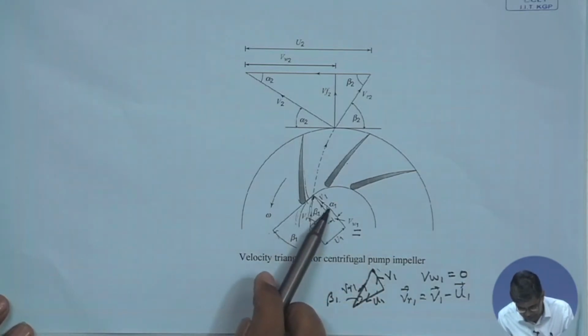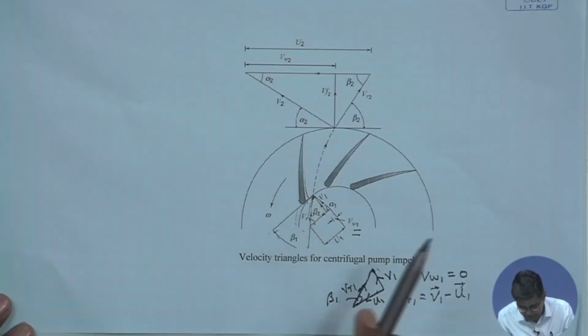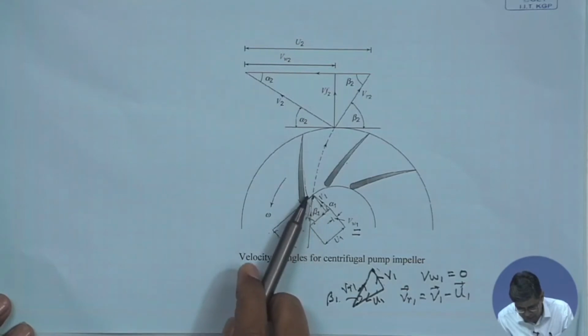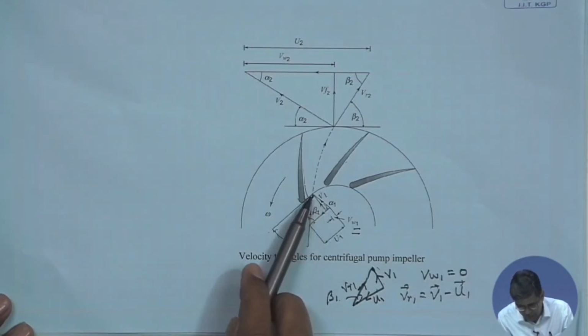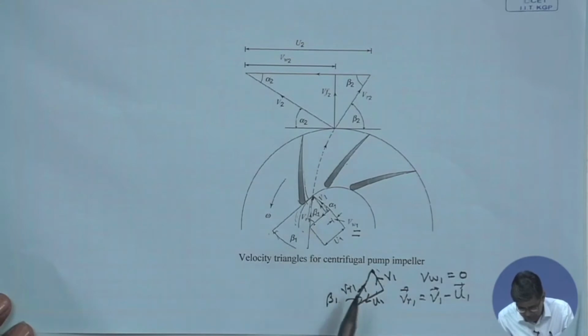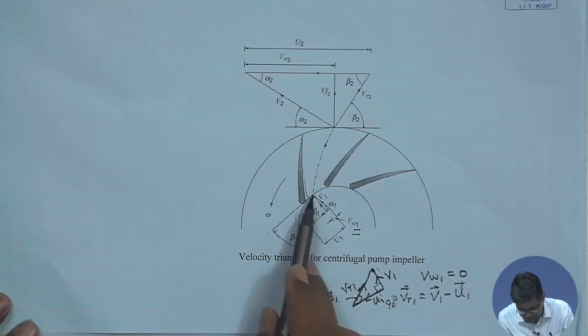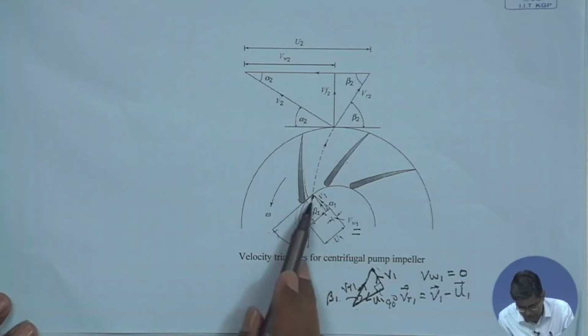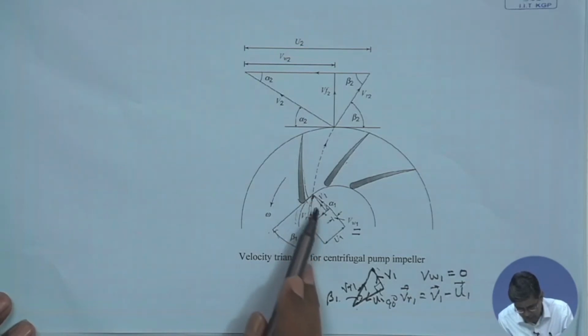So, that is why this line is given. In practice the velocity angle is like that. Nevertheless, it should be designed in such a way that even if this V1 is not perpendicular, the direction of fluid velocity is not perpendicular to the rotor velocity U, the ideal case is 90 degrees. Here also, in the ideal case, it is given by this line, but it has a very small component in the tangential direction. It has an appreciable component in the radial direction only, the flow velocity.